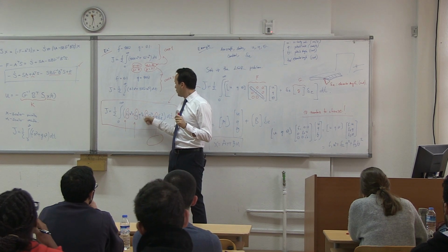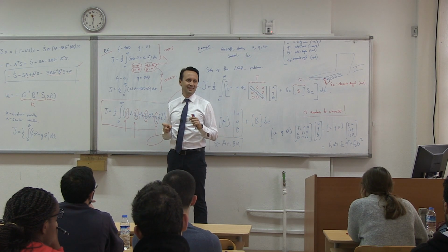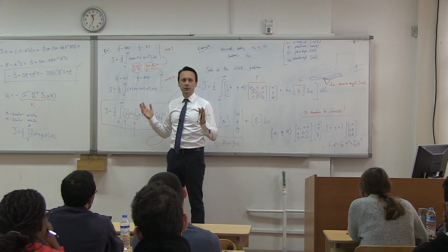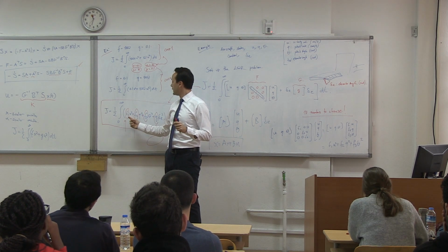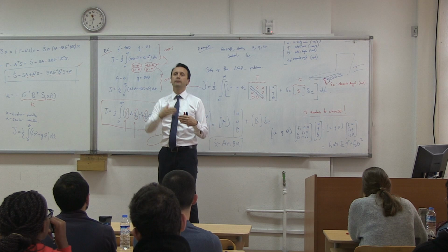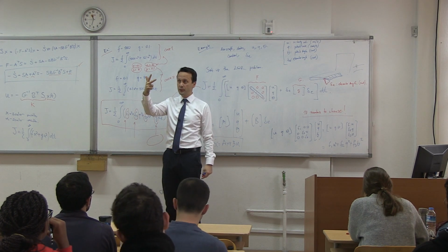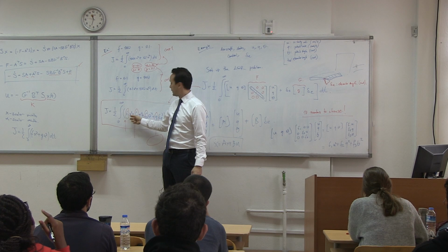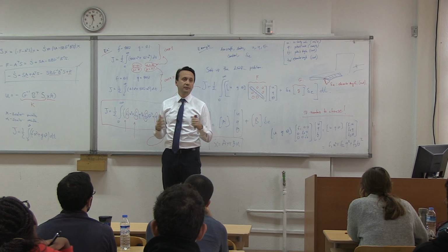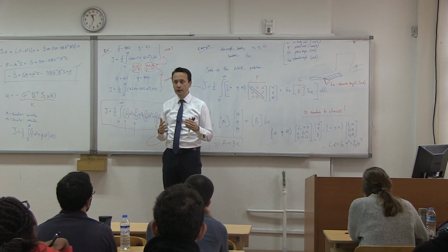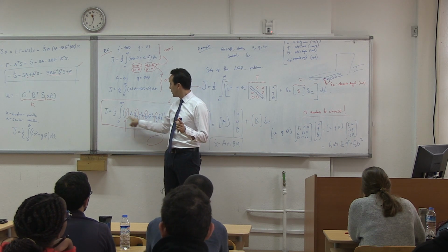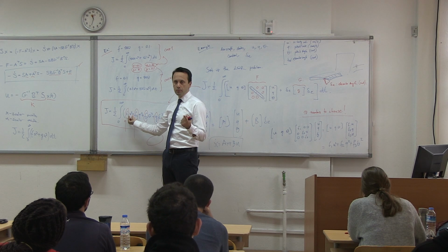Even if you put 1, 1, 1, 1 to all this, U will always be more important because it's a large number. The optimization problem will try to reduce U because any movement in U, let's say from 50 meter per second you go to 53 meter per second, it's already 3 meter per second, so it's a large number here. A large Q would be 0.5 radians per second. That's already quite large, right? And then you would multiply it with a small number. Even if you put 1, 1, 1, 1 over here, U will become more important.